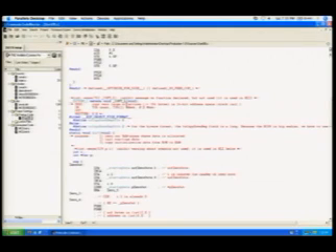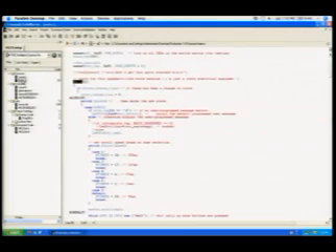Once you get into main, basically all you do is loop around. What he's done here is implement a state machine using a while loop and a current state. He's got all his interrupts for the keyboard handled as interrupts rather than polling the status, so he can sit in infinite loops while waiting for more input to occur. When it does occur, he just jumps over to that and then jumps back. It's very simple code, and it's very easy to modify if you know what it's doing.